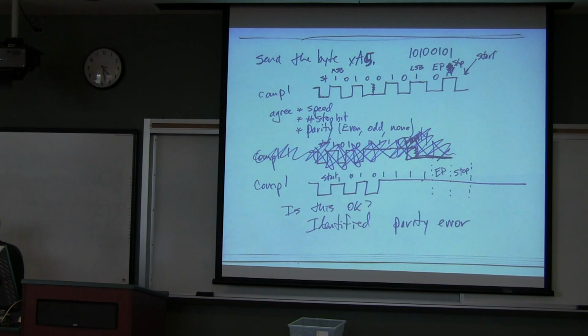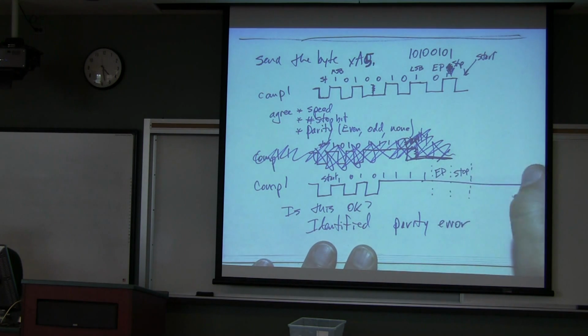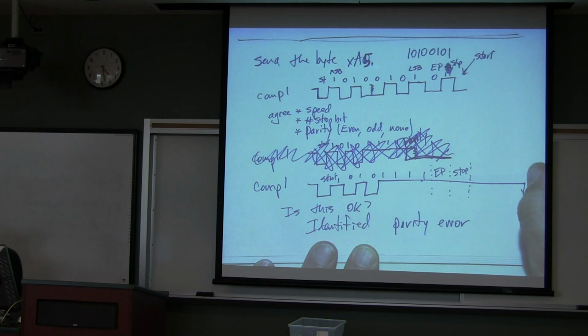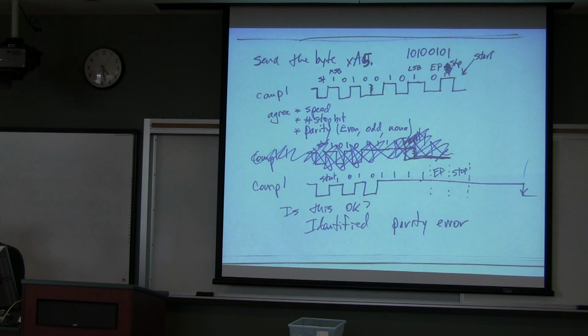And by the way, this is pretty typical. If you have a communications fault, it's usually not a single bit thrown here and there. It's usually a whole bunch of stuff. The other thing pointed out here is that there's no start bit. So when this finally goes down, that's when it would first say, here's the next thing being communicated.